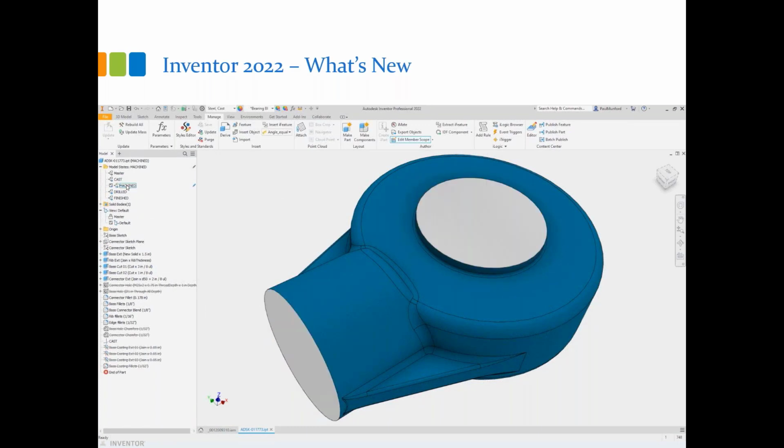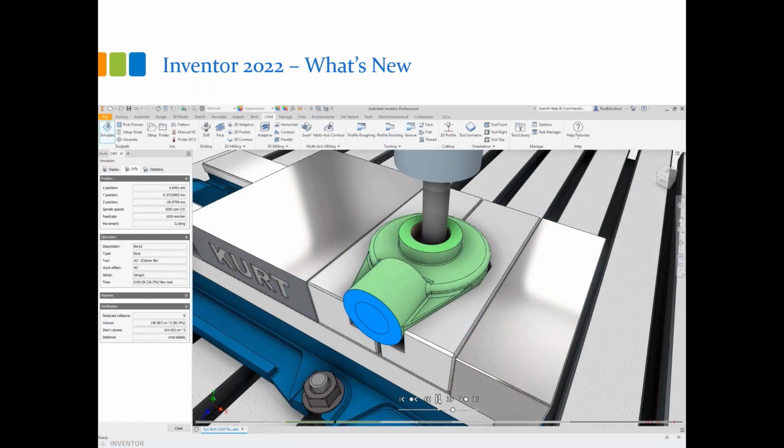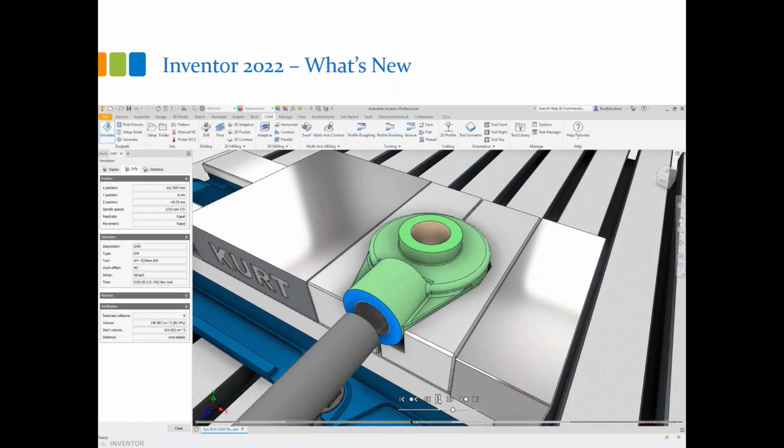Now, you can also edit these from Excel. So if you're making separate instances of the model states where they're incrementing by 1, it's very easy to go into Excel and do that and let Excel do the work for you and increment that by part numbers and everything else that it's doing with the equations, pulling from our parameters. This is fully supported in iLogic. It's fully supported for the Inventor CAM.